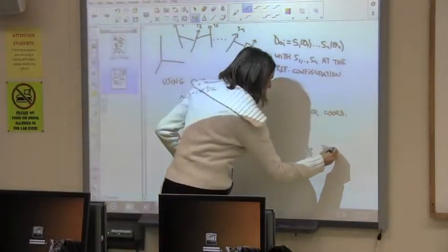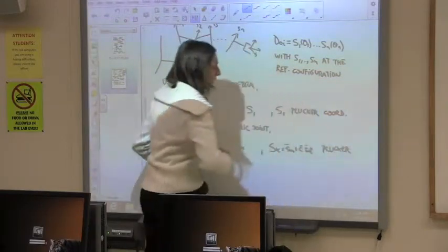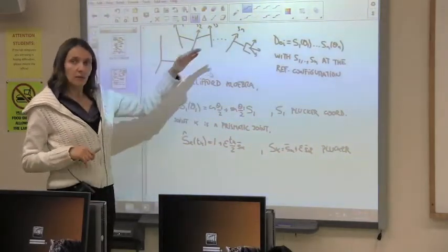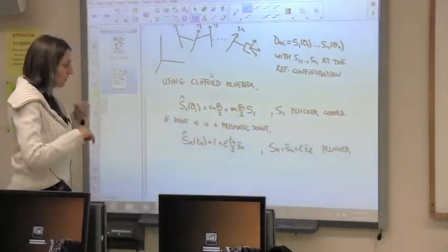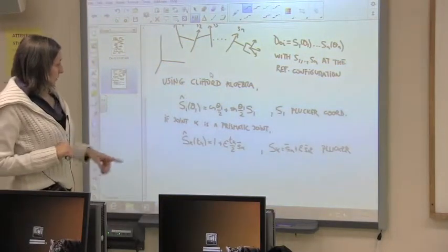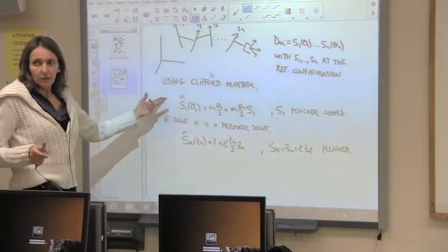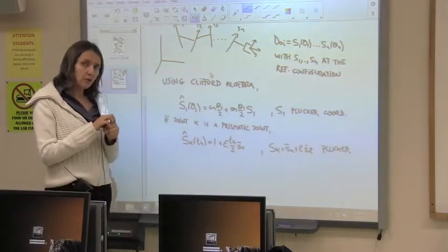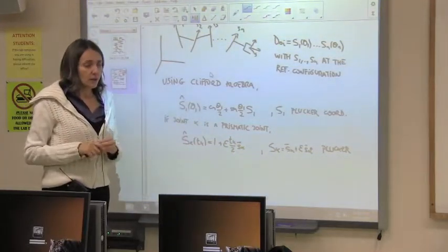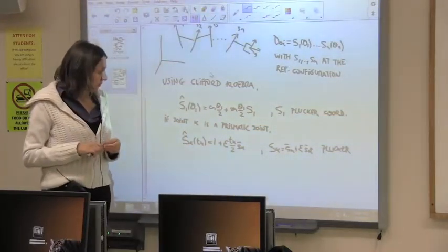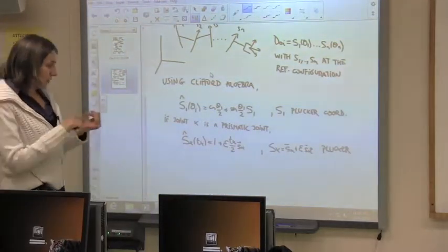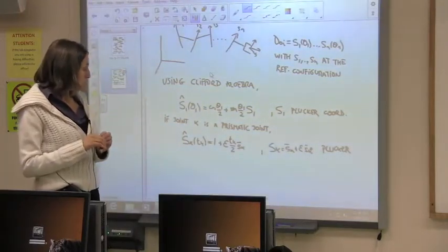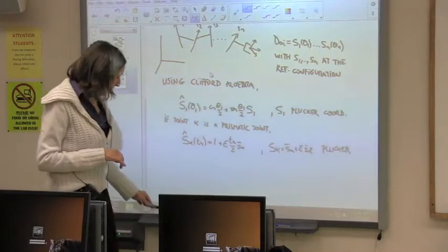So it's very easy to write these, what we call screw transformations about each joint, multiply them and get the relative forward kinematics. And we are going to do that as an example. These are just two expressions for normal joints. You can create the same expressions for spherical joints or for cylindrical joints. It's also very easy. They are in the notes, that you have there. There are expressions for the cylindrical, for the spherical, I think even for the universal joint, and they are all fairly easy.